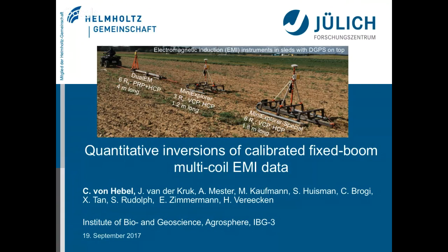There's another question. You just explained the calibration, but how do you know in advance the range of the expected resistivities if you don't know the subsurface? Yeah, it's a very practical question. So we start in the field and we measure the complete field. Then we download the data in the field, plot them, and see what the apparent electrical conductivity range of this test site is.